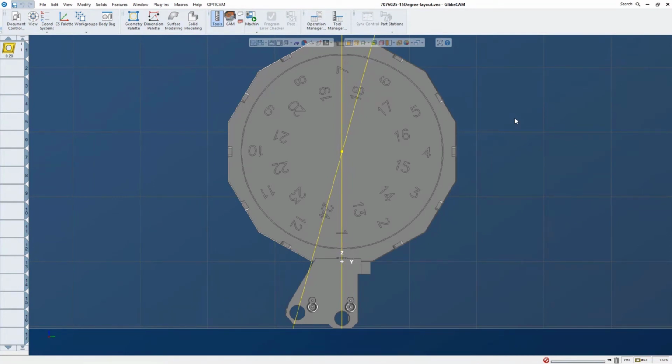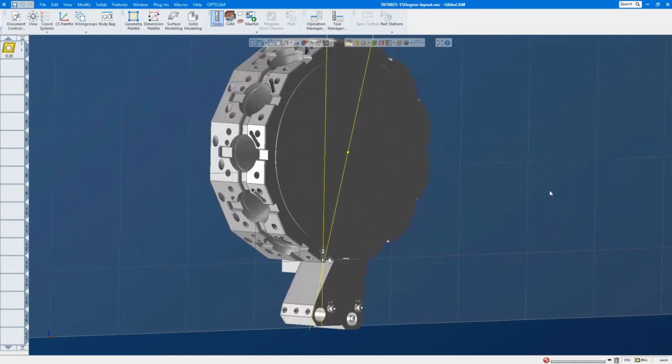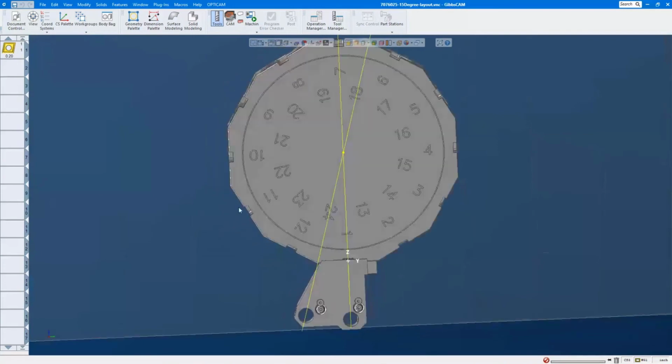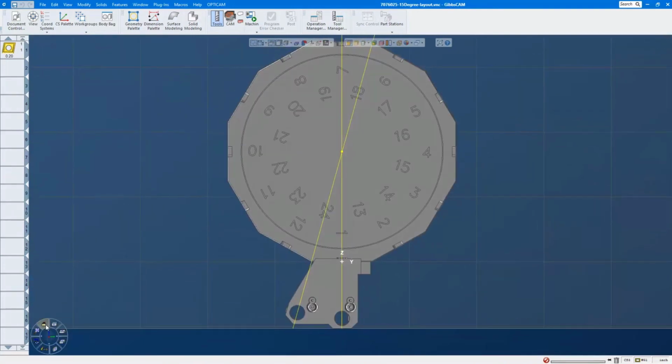When you have a turret like this, for example, that has 24 positions, the blocks are designed specifically for that turret. You can't exchange the blocks. It just doesn't work, even though you think you can. What we do is take everything from the center of the turret. You can see I've drawn a couple of lines here, and in this case this is a BT65 turret, which is becoming popular. This block is designed specifically for this turret, and it works. It's flawless, 100%.